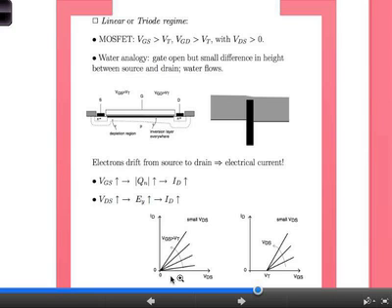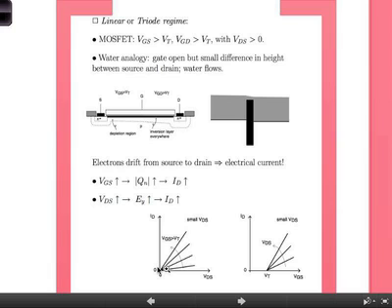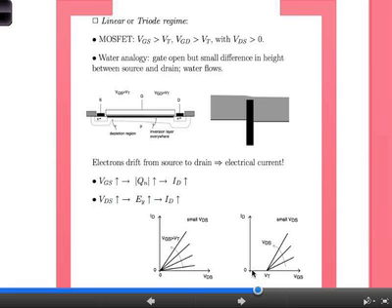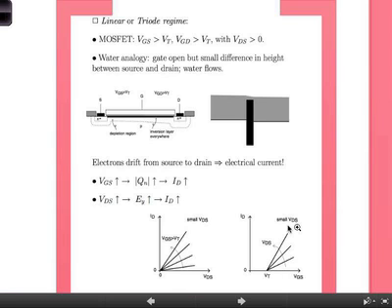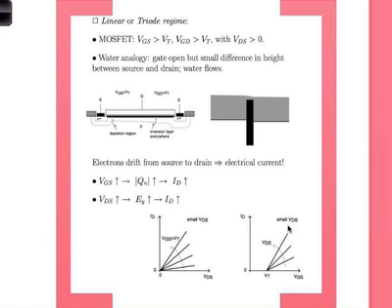So this is very similar to what we saw for the JFET before. We had something very similar. Okay? We had a different family of curves, but they're all straight lines essentially. The family of curves are for different gate to source voltages. Okay? And you can also plot the drain current versus the gate to source voltage. You can see up to some threshold voltage, nothing happens. Beyond the threshold voltage, you get a straight line. That's the difference. Now we have a threshold involved here.